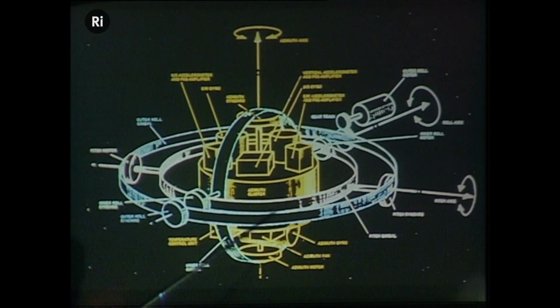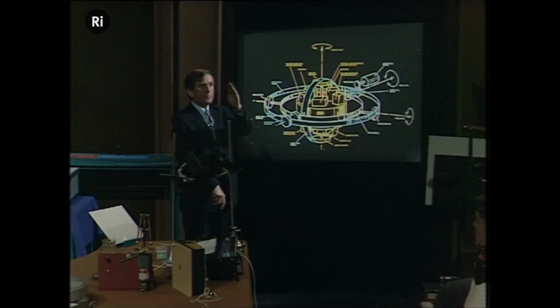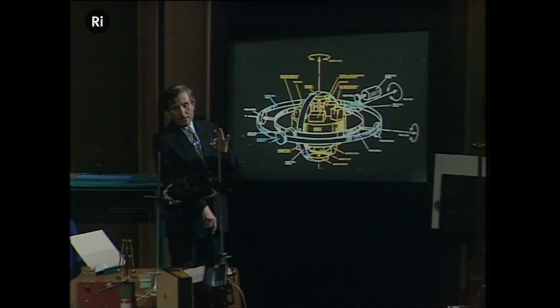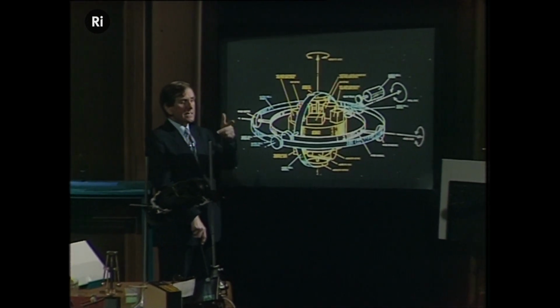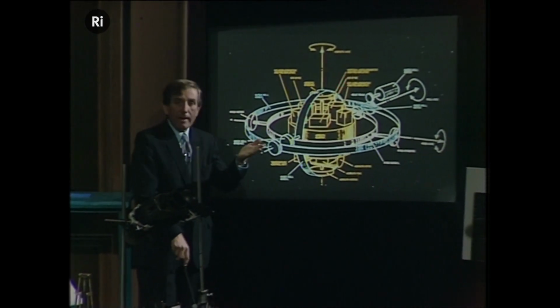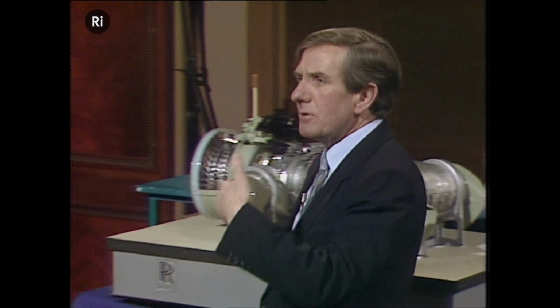The way it works is that the gyroscopes hold the platform very steady in space. No matter how the aircraft may move, they'll maintain stability to a very high degree. The platform carries 3 little instruments called accelerometers, and they measure the acceleration in 3 directions very accurately again. So if you measure the accelerations, then you can compute the velocities, compute the displacement. Provided the thing is set up correctly to begin with, it can register the actual position of the aircraft without any external references at all.